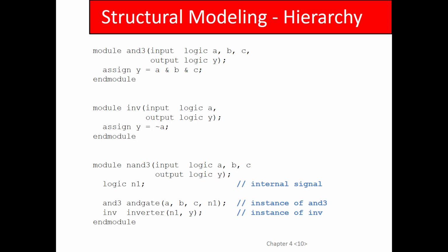So this is very common. I don't know if you guys use SPICE in your circuits class, but SPICE uses the same idea. When you do a SPICE net list, it works exactly the same way. Wires are connected through common signal names, right?